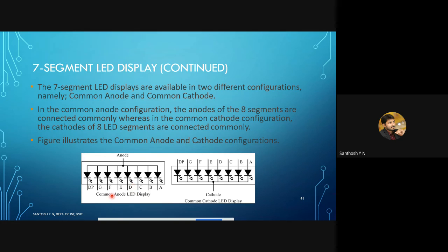So we can connect these 7 segments in two configurations, that is common anode and common cathode. In common anode, all the anodes are shorted together and connected already to the port pin, and for the port pin we are providing logic high. In case you want to activate only A, B, C, and you do not want to activate D, E, F, G, and DP, then you will connect the negative terminals of A, B, C to the negative terminal of the battery. I mean to say that the cathodes of A, B, C will be connected to the negative terminal of the battery. So what you are understanding at the last: already the anodes are provided, so in order to activate, you connect A, B, C to the negative terminal. Whichever segments you are interested in, only those segments can be activated by providing those concerned cathode terminals to the negative terminal of the battery.